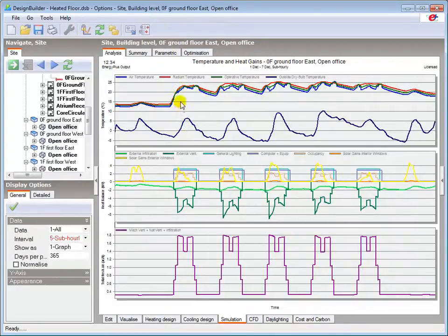Zone temperatures are generally less stable due to the response lag from the underfloor heating system. Note the spike in temperature after Wednesday and Thursday lunchtimes, with high solar gain and reduced nat vent from lower occupancy. This further highlights the slow response time of some underfloor heating systems, as it takes time to release the thermal energy stored in the mass of the floor slab.